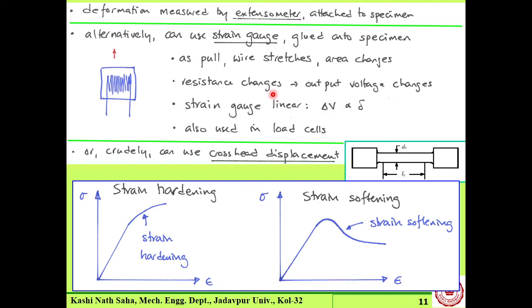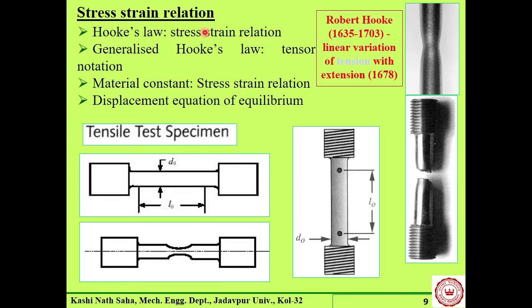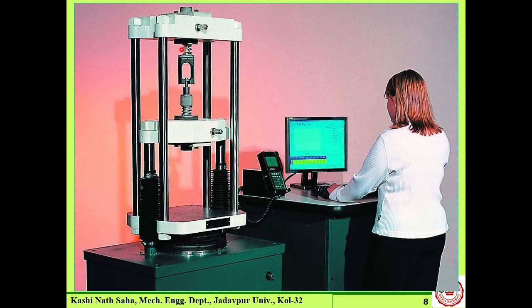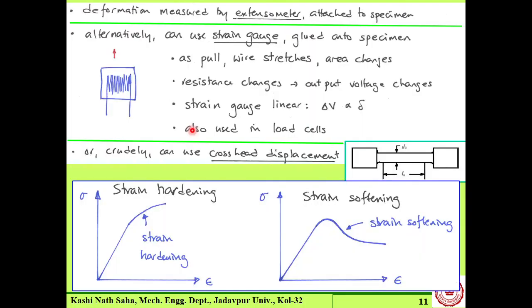The other measure is the load. For measuring this, we can use a load cell. Here you see this is a sort of load cell, or it can be on top of that also. Or in this case, if the diameter of the plunger or piston rod is known, and we know the fluid pressure, then also we can determine the load. So that is what we measure.